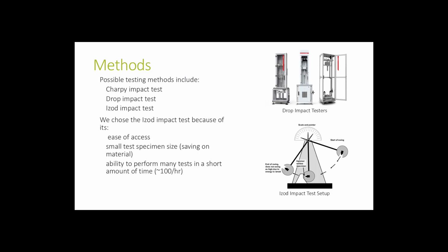To test the break energy of these 3D printed parts, we had a few options to choose from, primarily a Charpy impact test, a drop impact test, and an IZOD impact test. The Charpy impact test involves swinging an impact weight pendulum into a test specimen held at both ends. A drop impact test involves strapping down a plate of material and dropping an impact weight from a specified height into the center of the impact specimen.